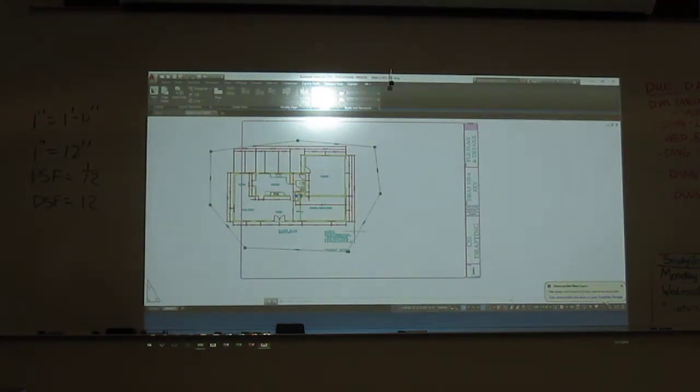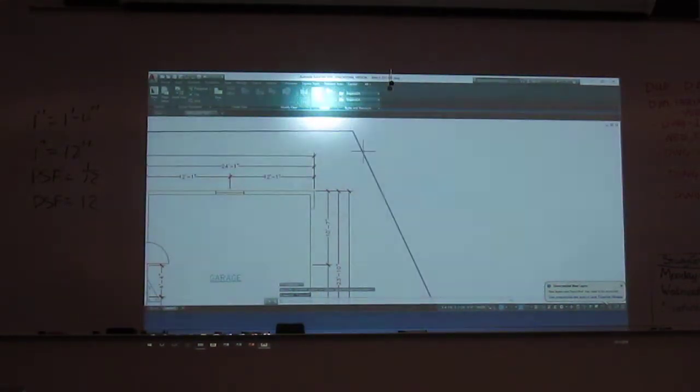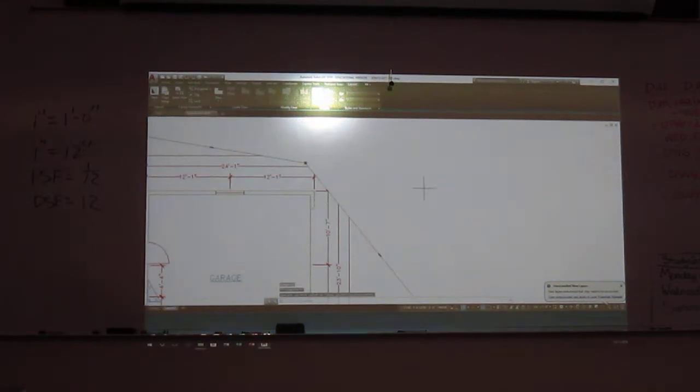Okay, so I've got this thing to the correct scale. Now all I do is select it and move my nodes around so that I display the entire object as I wish it to be displayed. The thing you want to watch for here is around these edges, you don't accidentally have that, where I've chopped off all this stuff that's outside the viewport. So just make sure you're searching around the outside and you see the full extent.